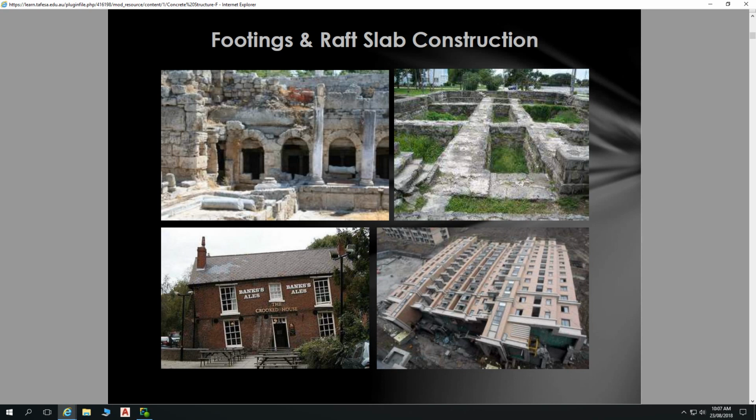That's going to be the same in any of the elements you see around the building here, to a degree. So the mullions for our window there, now there shouldn't be any load placed upon those windows, but if there was, then those mullions are going to be in compression. But they're not just simply in compression, they're going to want to deflect one way or the other. If they deflect in one fashion, then the short side of that is going to be in compression, the stretched side is going to be in tension.